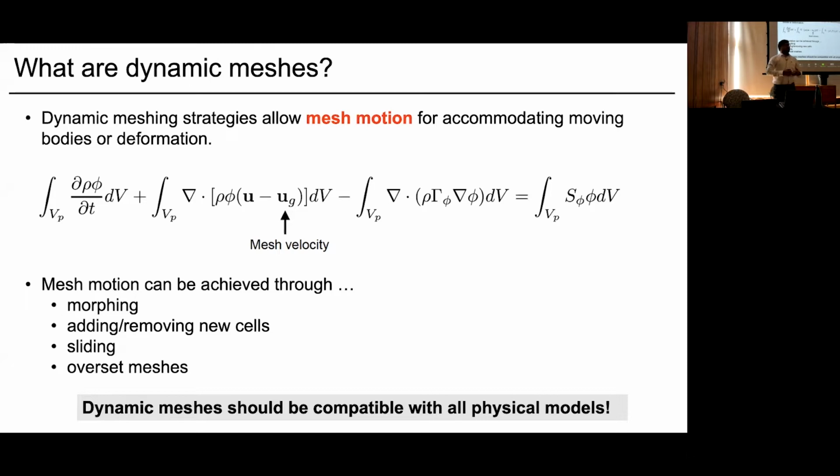So due to this mesh velocity, we need a strategy of moving the mesh in different ways, and which automatically means that when the mesh is moving, or especially when the mesh is morphing, the volume of the cell or the shape of the cell is not remaining constant, which is changing with time. So of course, inherently, we need more stringent numerical conditions for this kind of moving mesh problem than in comparison to a static problem.